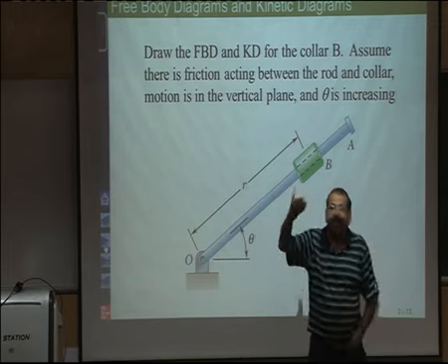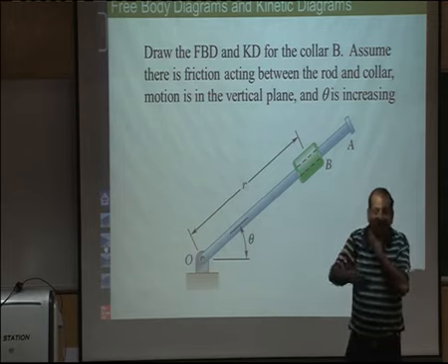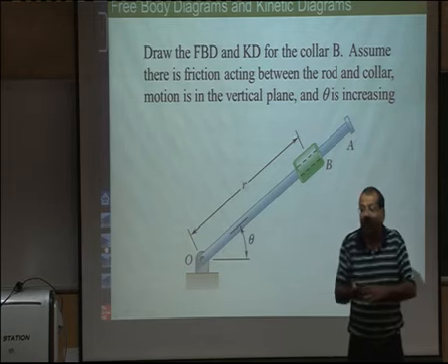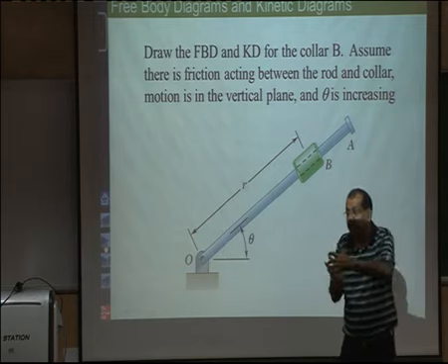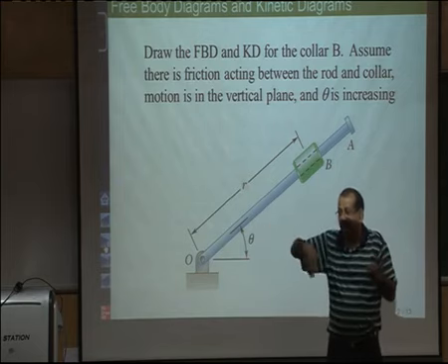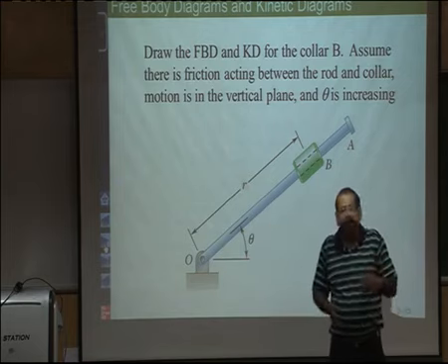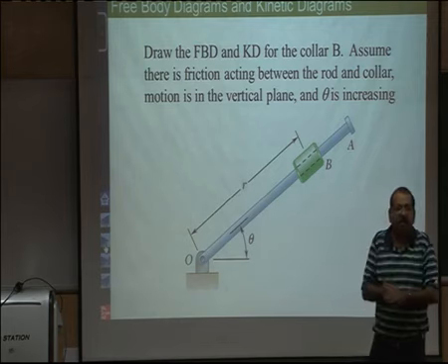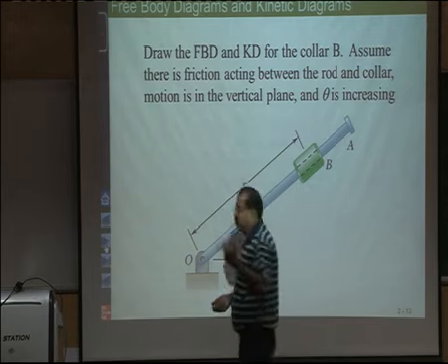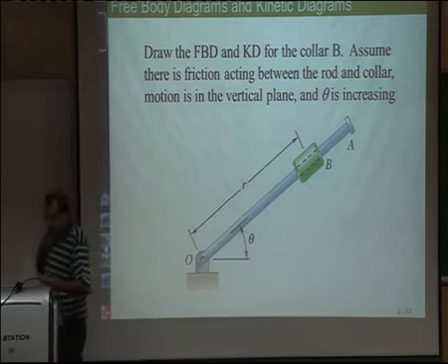Now string tension had to act on only one of the two bodies, not on both, and therefore the answers would have come out wrong if you showed it acting on both the bodies, because when you combine both of them, the tension acts only on one of them, only a single tension. Whereas if you show it acting on both, and when you combine these two, you will get 2T, and that was the mistake.